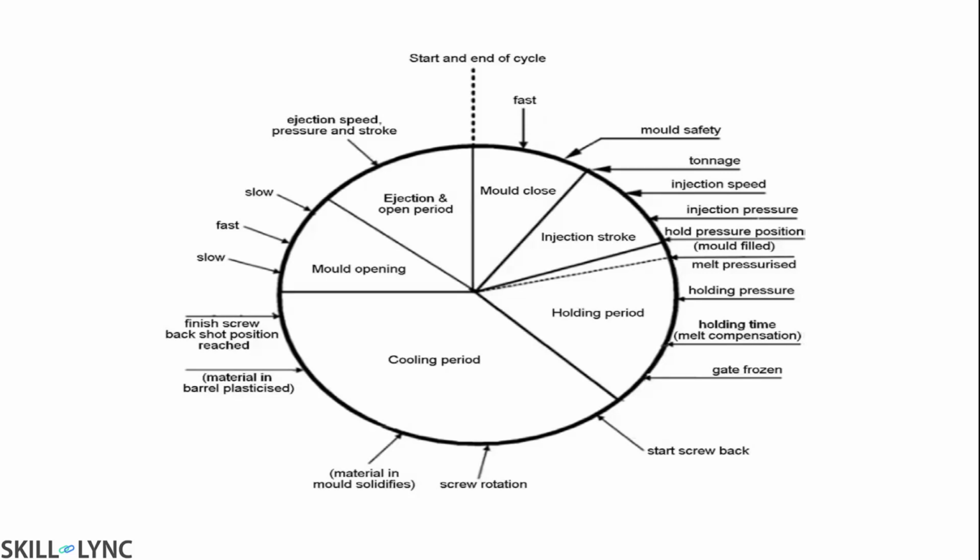So these are the stages involved, followed from mold closing, injection stroke, the packing period, cooling period, mold opening, and ejection methods. These are the basic ideas of the cycle time calculations.